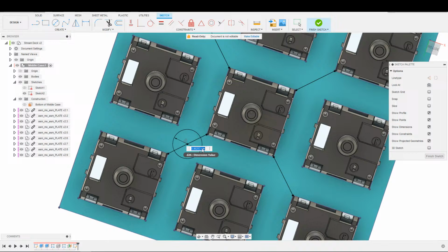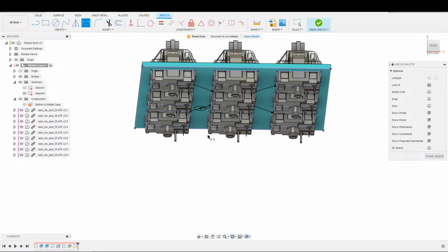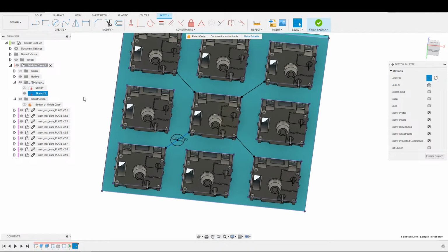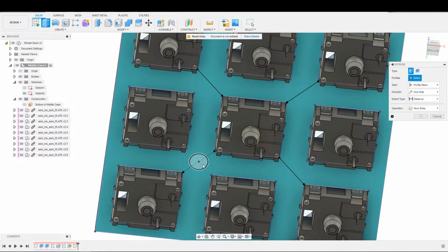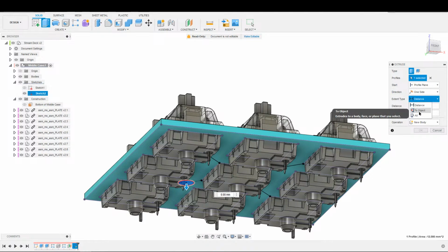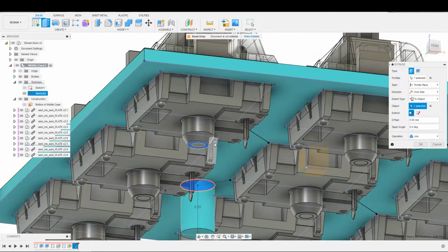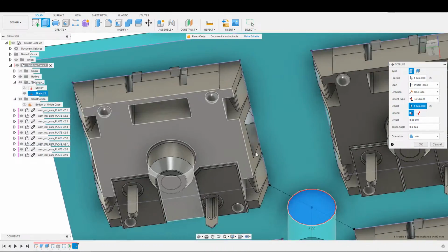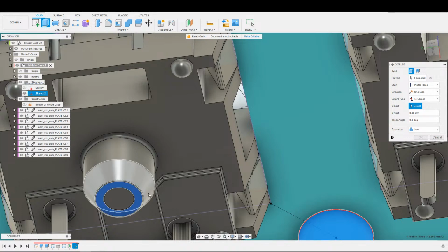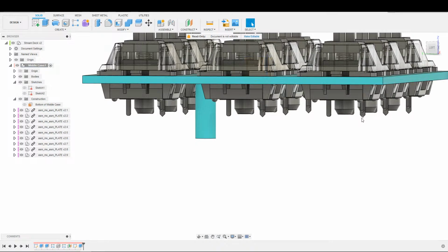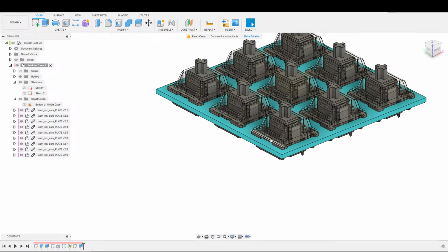Because again, at this point, I've talked myself into just having this be a regular standoff and not actually fastening the middle case to the base, just having it pressed in, sandwiched in between the top and the bottom. So, since that's the way we're going to be doing it, there's no sense in putting all the effort into everything else. So again, down to the face, and actually I should, just for the sake of sanity, use this guy. This is the original guy over here. So just to make sure nothing goes wrong ever, we're going to do that. And again, I'm going to just add another 5 millimeter, should be fine, standoff for wires to go underneath the buttons.